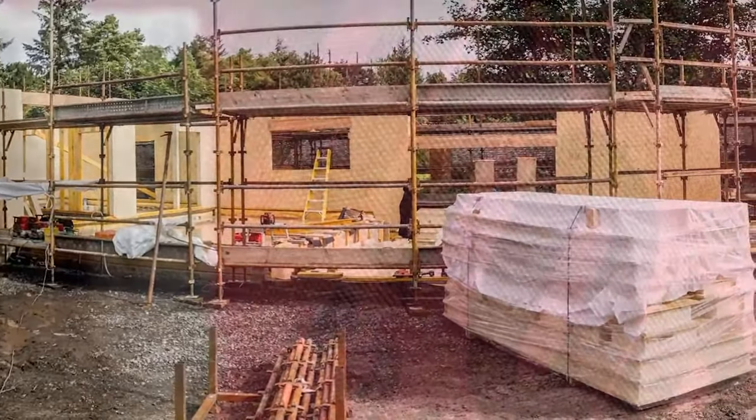The common structural elements of a pitched roof consist of trusses or rafters, over which are laid an underlay membrane, then battens and tiles or slates as the final waterproofing layer. Some types of roof, and most roofs in Scotland, may also include a sarking board over the rafters, with the membrane laid on top of this. This stiffens the structure, making it more resistant to wind loads, and also facilitates the traditional Scottish roof practice of fixing slates directly to the sarking boards.